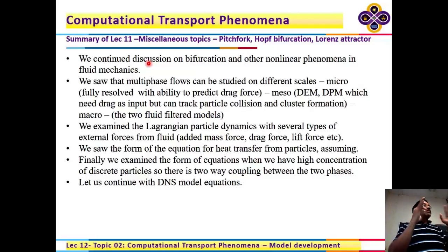But when COMSOL solves this, it is not going to make this simplification. COMSOL is going to calculate all these gradients by discretizing them. But it turns out that since there is no variation, these will all be to machine precision 0. Similarly on the right hand side, dp/d theta will be 0. Why is dp/d theta 0? Because of the symmetry in the problem. If you look from the top, if I start from this point and go around and come back to the same point, pressure at any point has a unique value, right? So the pressure cannot change as you go in the theta direction. So this term would be 0 by symmetry.